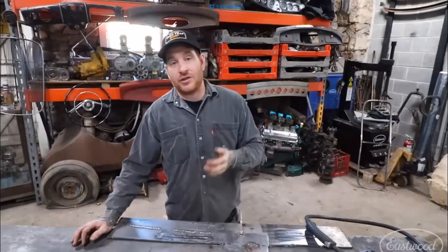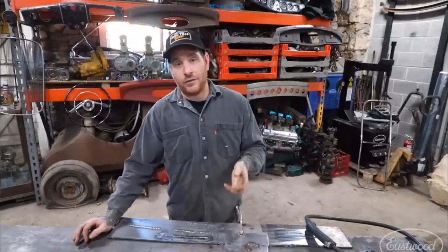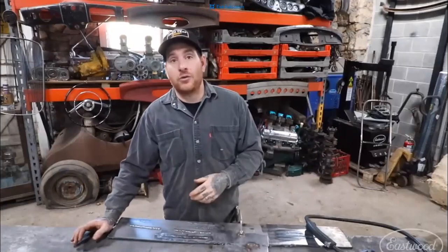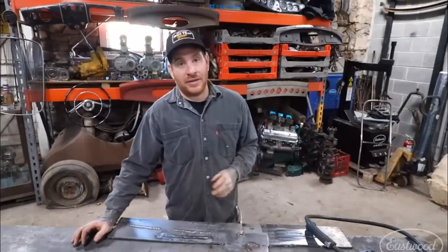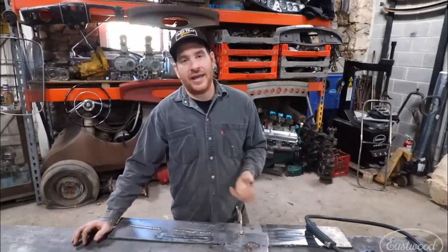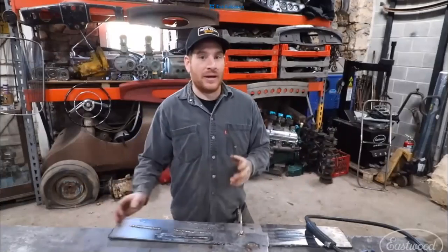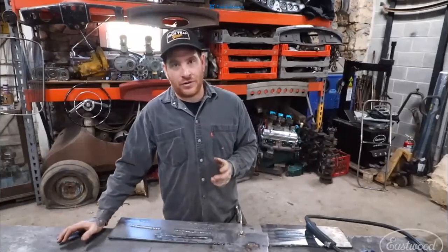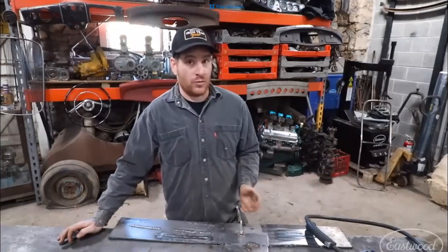The most common thing also is 110 welders because it is so simple to get an extension cord. If you're running a long extension cord, like 100 foot or 200 foot to your welder, do realize that you're going to be dropping in power by the time it gets all the way to your welder, and you can't use an extension cord like you would use to run your Christmas lights on your house. By the time the power actually gets to your welder and the draw that the welder has, you're going to have issues with your welder where you're going to get poor welds, maybe your welder won't even turn on.